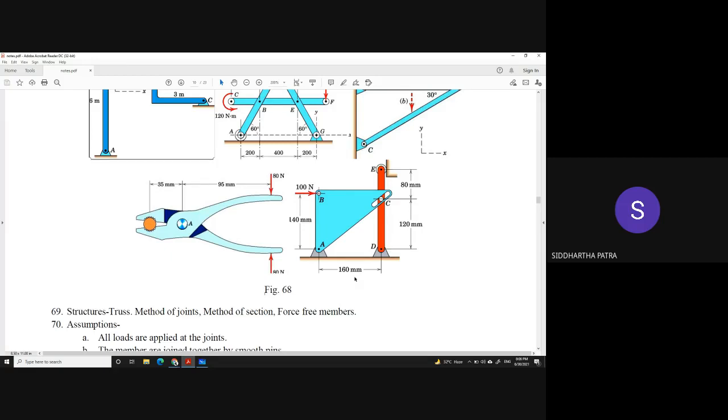3 which are absolutely rigid if the entire structure could move like a rigid body, and 2 which are the relative motions of DCE with respect to ABC. So there are 5 degrees of freedom. And therefore you need 5 constraints coming from the ground just to keep the object in equilibrium under the action of external forces.